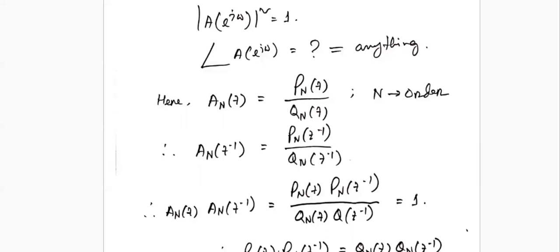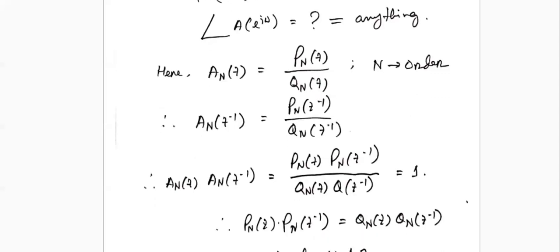So from the pole zero point of view, the transfer function of an all pass filter can be written as P(z) over Q(z). Like this, H(z), the transfer function, can be written as Y(z) divided by X(z). That is the simple concept we know. So any transfer function can be represented by the zero locations and the pole locations. Similarly, the inverse function can be represented by this.